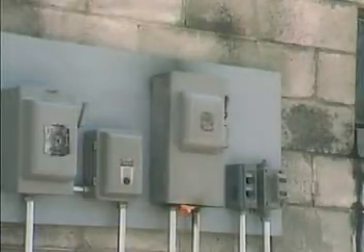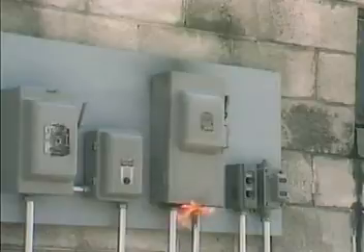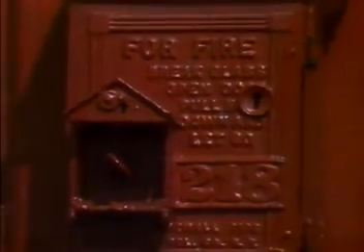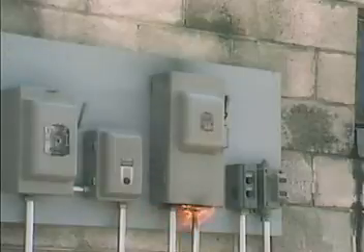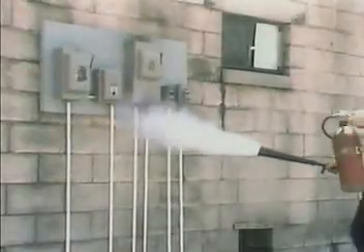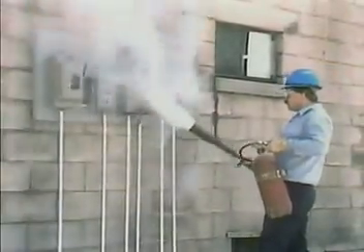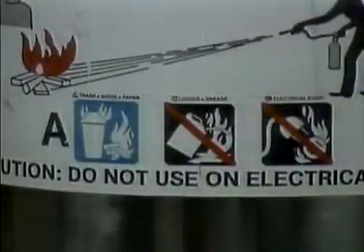Another hazard that you may have to deal with is an electrical fire. Electrical fires can happen for many reasons, and it may be part of your job to respond to them. Generally, the first thing to do is report the fire. Reporting the fire will set in motion other emergency actions, such as isolating circuits to prevent injury and equipment damage. Then try to cut off power if possible. This takes away the source of ignition. If you're going to put the fire out, be sure to use the right type of fire extinguisher. Fire extinguishers are classified by the type of fire they're designed to extinguish.